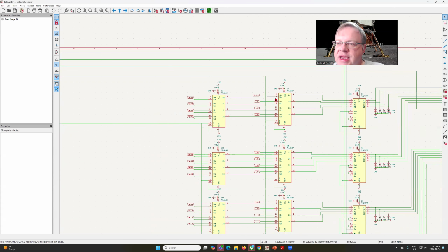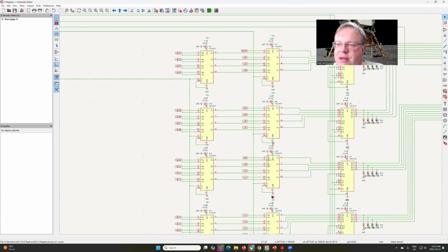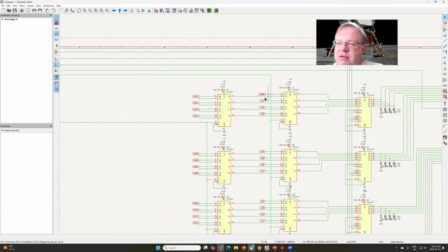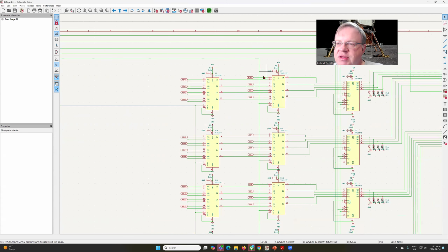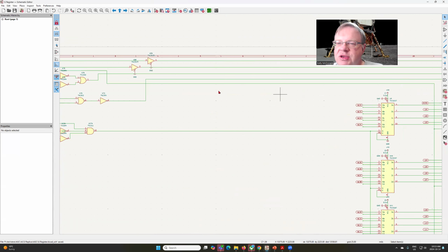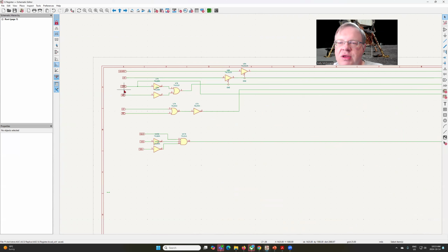Now, the data that comes into the G register is a little bit different. We have a couple of options. We're using a couple of 4-bit, or basically quad 2-to-1, selectors here. We've got one set here where if we go 0, which is tied, you can see, all back here to our L2DG control pulse.